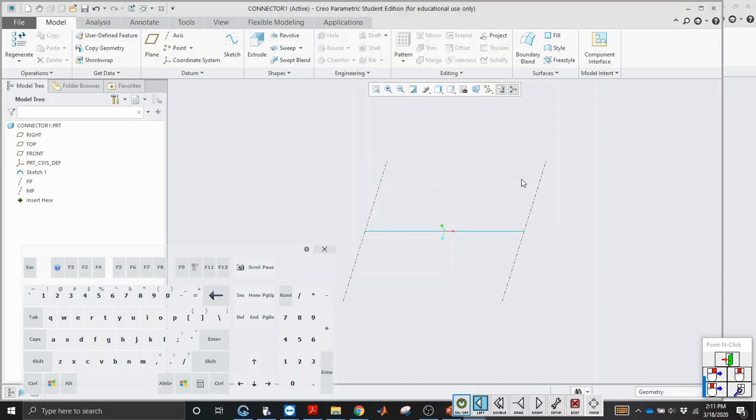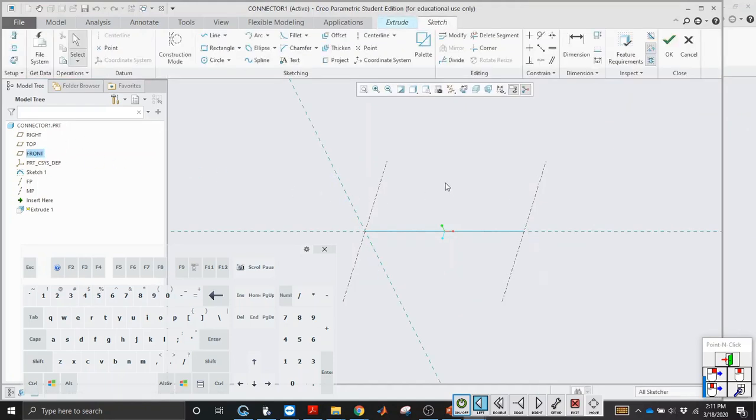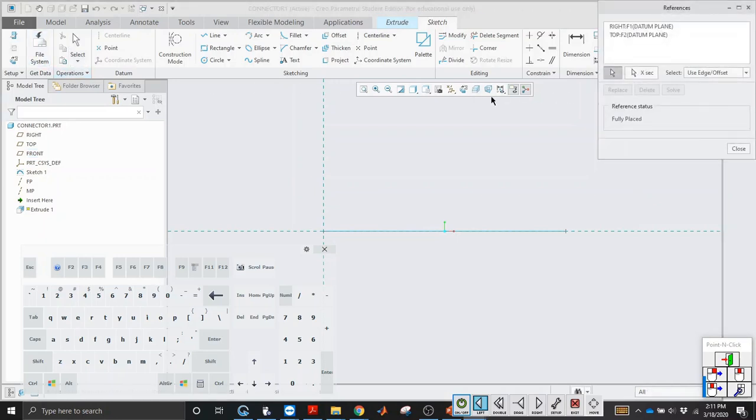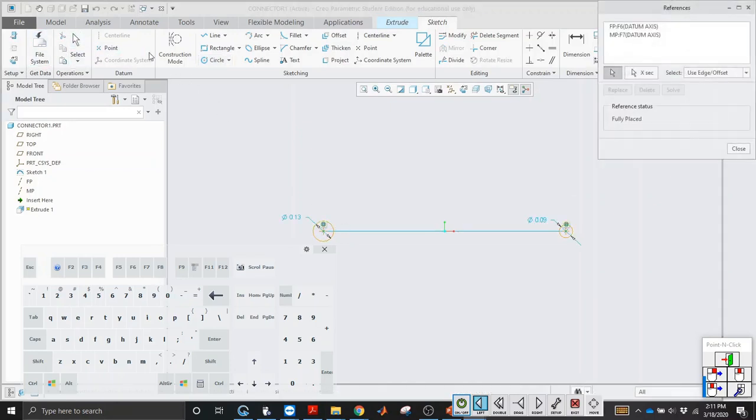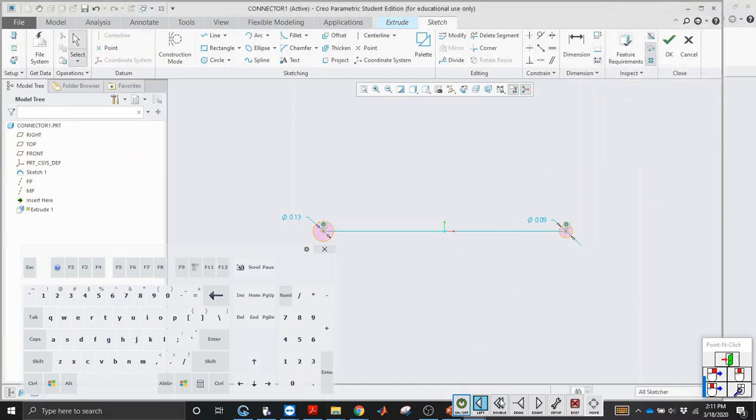So now that we have our axes that the pivots are going to go through and our skeleton, we can go into this, not a sketch, wrong button. We can go ahead and extrude off of the front datum plane. So in our sketch model, we drew those axes, and we now want to use these axes as our references for this. You'll see why in a minute. Let's stick with the same. It didn't select. All right, cool, we're good. I wanted to avoid selecting the actual sketch. So let's go 0.375 again, just to keep the same.